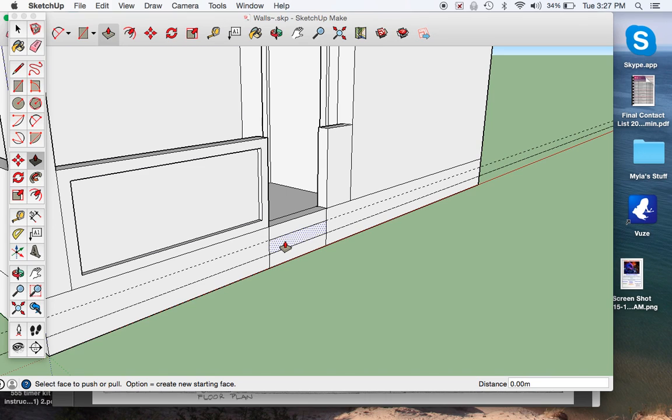And the run means the actual step that you step down on, and usually it's a little bigger size than your actual shoe or step. And so this one we're going to make it 300 millimeters, and so what we'll put on here, this one is 600, and then we'll make this next one 300.3, and there you have your steps going up.